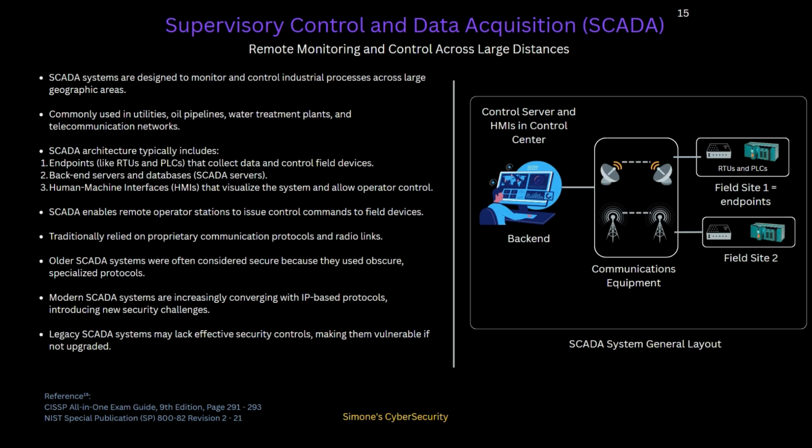Now, one of the biggest advantages of SCADA is that it enables remote monitoring and control. So operators sitting in a centralized control center can send commands across vast distances to open valves, close switches, or adjust system performance in real time.